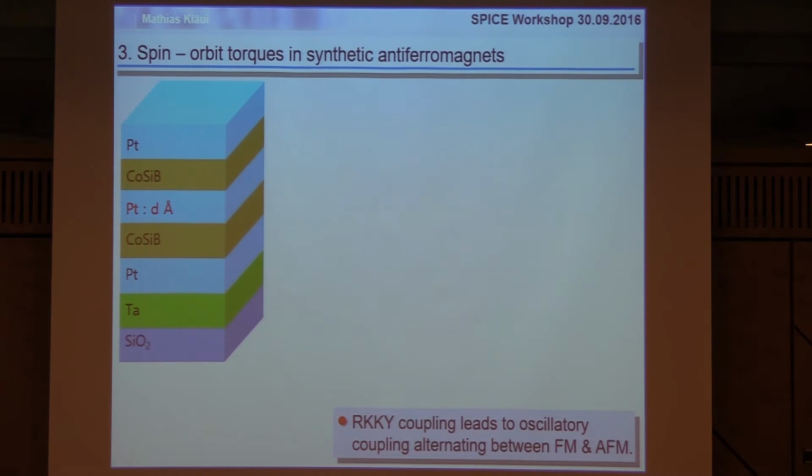So by varying the thickness of the platinum, and that's something that was also new to me. Everyone uses ruthenium, but it turns out that platinum also mediates the RKKY interaction. Again, look at Stuart's 1996 papers or 1999 papers. He's gone through the whole periodic table and measured RKKY, and it turns out lots of the materials show RKKY. Just ruthenium is better and is stronger, therefore everyone uses ruthenium.